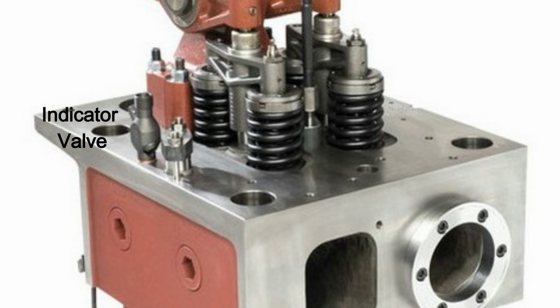Before starting a large diesel engine, the indicator valves are often kept opened while turning the engine slowly. This helps check whether any water, fuel or lubricating oil has accumulated inside the cylinder. If any liquid is present, it can be expelled safely before starting through the indicator cock, which prevents serious engine damage due to hydraulic lock.